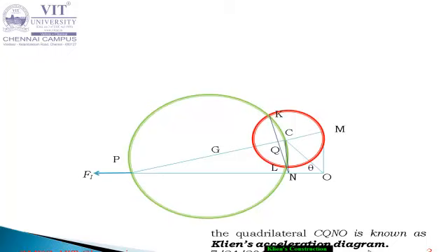The connecting rod is a rigid body, and it does not have a uniform cross section. So the load or the solid material or weight may be concentrated in different places. So we have to solve by using a dynamical equivalent problem. The entire mass of the connecting rod may be divided into two masses, concentrated at two points. One is concentrated at one end, that is at the piston. Another one is where it is concentrated, that we have to calculate.